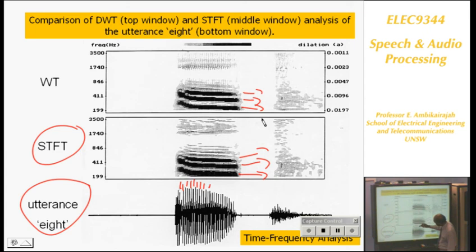That's the time resolution. The distance between pulses, the short-time Fourier transform does not hold that. Here, look, there's no time resolution. It's all smeared there. In the wavelet transform, don't you see here? It preserves the time resolution positions. That position corresponds to that position. So if there's a transient in the wavelet transform, if there's a time resolution, it will hold that. Whereas the short time Fourier transform smears it because of a fixed window, where here there is a variable window. Therefore, you can see here are pulses, tiny pulses. You can see here is there, where here is all smeared.